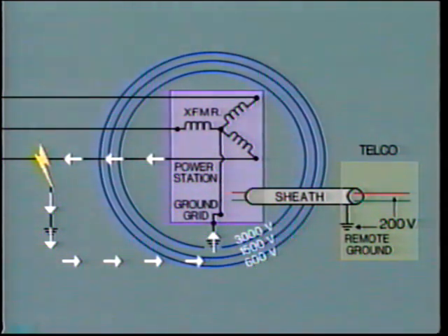Imagine a technician with one hand on the locally grounded cabinet door and the other hand on an incoming telephone terminal which is grounded remotely. If the ground potential difference is high, the resulting flow of current through the technician's body could be lethal. I'm sure you can think of many other ways in which you could put yourself across local and remote ground when working on telephone circuits. So, safety of personnel is a vital issue in this problem.